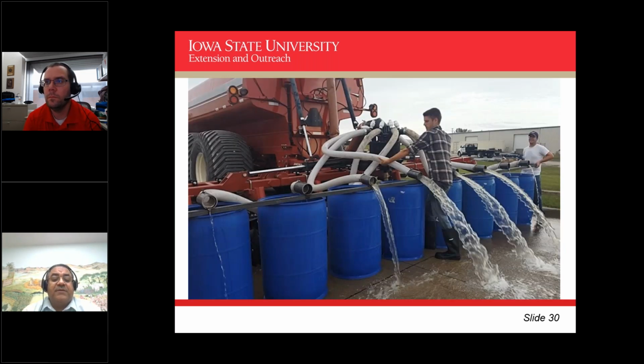But you guys saw this picture earlier where the variability is just dramatically high. And if you pay quick attention in this picture, you'll see the discharges in the hoses where there's nothing coming out. Those hoses are actually draping down below the toolbar on the back side. So on low application rate, what really happens is there's not much pressure in the manifold chamber.